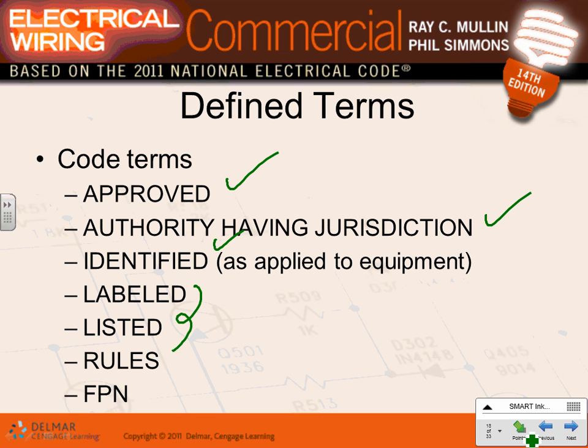This is for equipment. Your equipment has to be labeled and listed before you install it. You have a NEMA enclosure right here on the wall, right? You have to have a UL listing and labeling on it, otherwise you cannot install it, inside or outside. So equipment has to be labeled, have a label on it, listed on a list. Otherwise, people will use a coffee can as a lamp holder, right? Because it's very creative, cheaper.